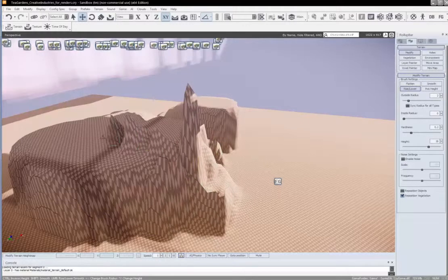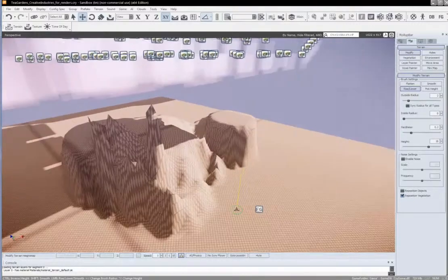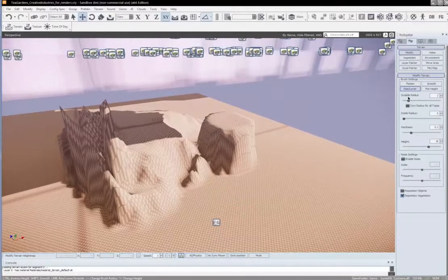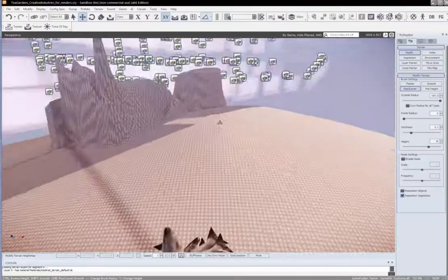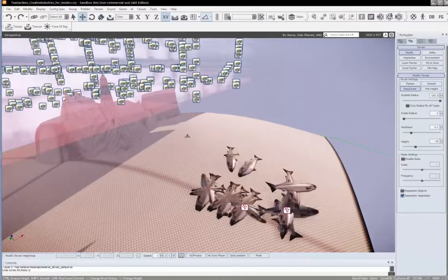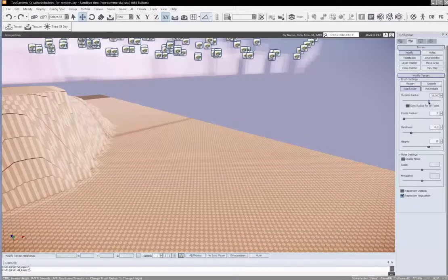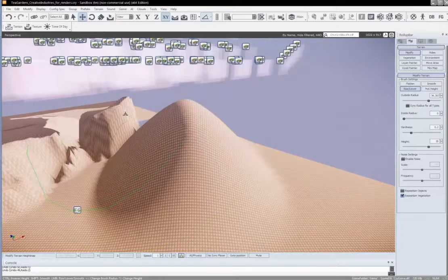You can make these cliffs and jagged mountains and things. It's just like Photoshop, where there's a brush. You can change that brush size with these radius options here. I'll max that out to 200. Now the brush is quite huge. If I click, it's raising the whole thing up. So I'll undo that, and then go back down. Maybe I'll put it on 100 or 30. Yeah, it gives a better sense of what's going on.